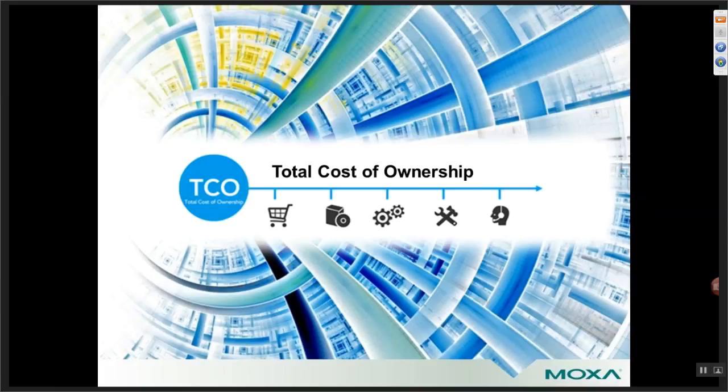Rich. All right. Well, that's a good question, Dan. So while both serve pretty much the same purpose as far as monitoring and maintaining the network, there are a couple of important differences. First of all, an enterprise network management system is going to visualize the network from a logical link perspective, whereas an industrial network management system is going to show you the physical connections between the devices. And this makes it much easier to troubleshoot hardware problems in the field, and it's also more consistent with how SCADA systems show connections.